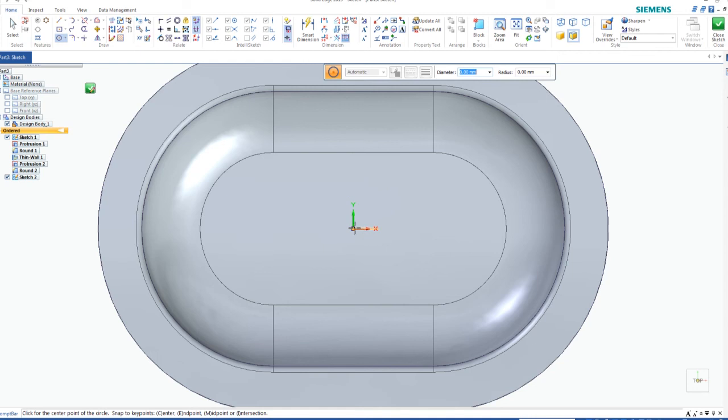Find the absolute center right here. Left click, drag. Don't worry about the size for now. So left click, and then put your cursor on the center, drag it, and there's a red line that follows right there. Left click again, drag, and then left click one more time. Again, don't worry about the size.